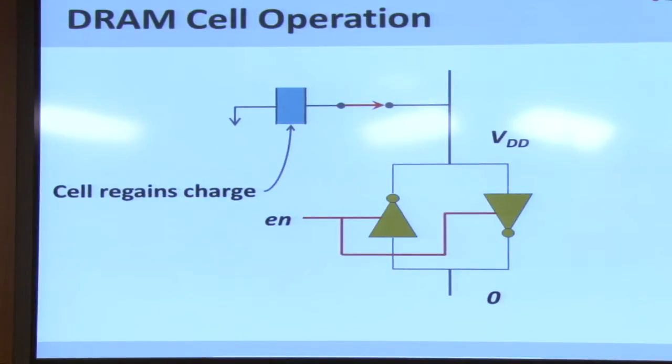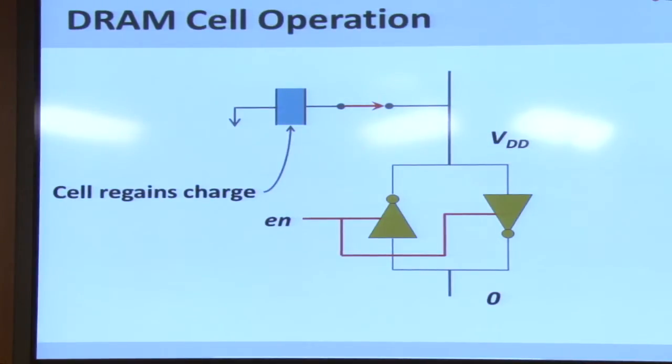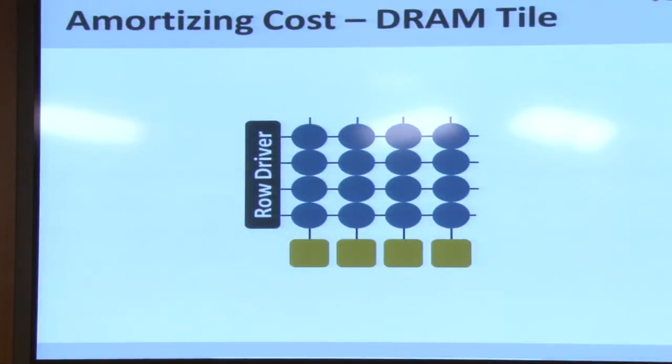Expensive, right? So even if you have, let's say, one cache line, which is 512 bits, the logic that we need to build to control that one access transistor is expensive. So we want to amortize the cost of controlling that logic across a wide number of cells. And similarly, we also want to take the sense amplifier and amortize its cost across a large number of cells, which is why DRAM manufacturers do this.